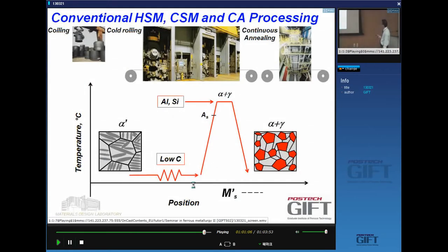For the cold rolling, if you use the martensite route, you will need the reverse martensite route. You'll need to have a very low carbon martensite. Otherwise, you'll have mechanical difficulties. The intercritical annealing is not a problem, certainly not with these aluminum additions. I've shown you that the best conditions for the annealing are very close to what is industrially used, and the cooling is not very critical in terms of cooling rates.